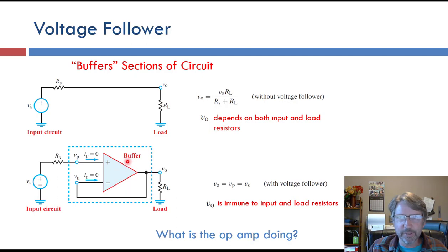It's called a buffer, or voltage follower. We have the op-amp here, and the output voltage is tied directly to the inverting input, and that's not connected to anything else. And so the analysis is basically using the rules that we have.